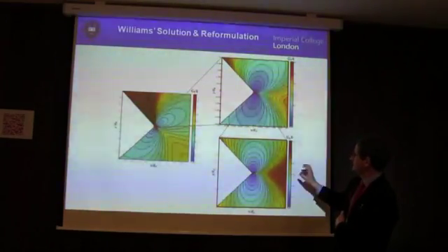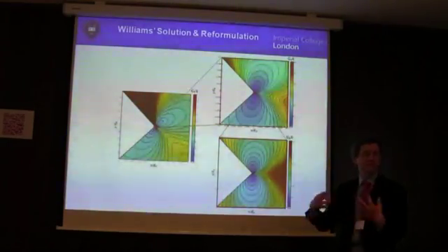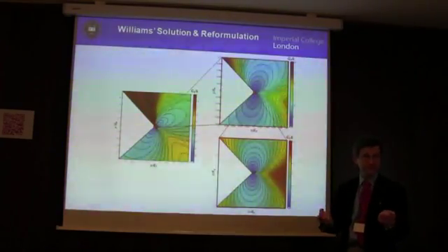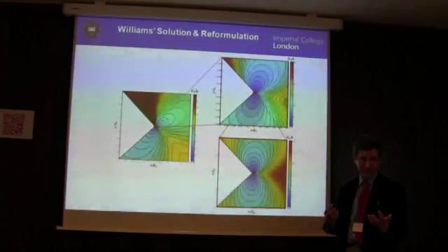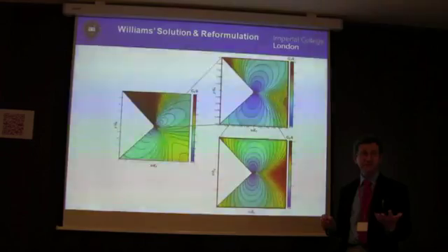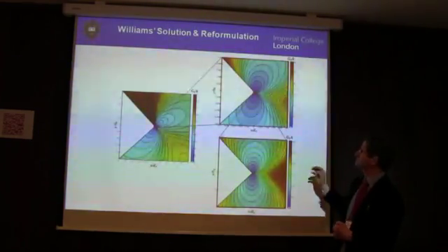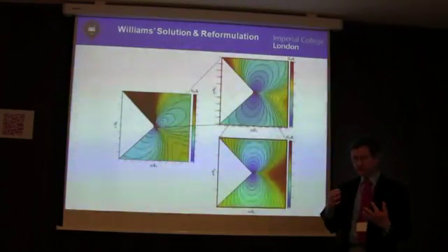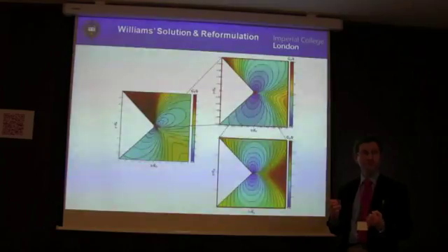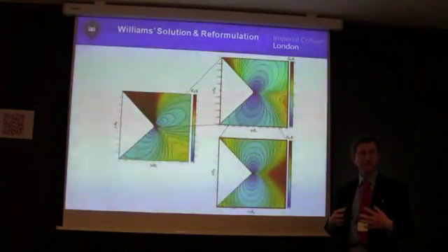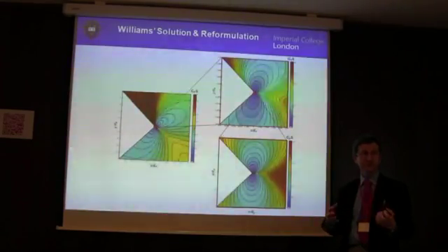And the colour scale is, of course, the magnitude of the loading. It's G naught, this multiplier on the solution that you can calculate straight away from K1 and K2, normalised with respect to little k, where little k is the yield stress in pure shear. So what we're talking about is looking at the way the notch root process, plastic zone, changes character as the magnitude of the applied load is increased.